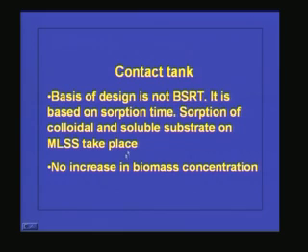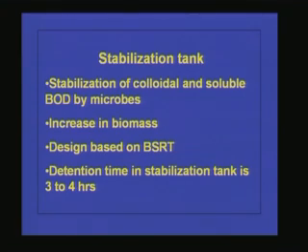And sorption of colloidal and soluble substrate on MLSS takes place. Though there is a slight increase in the biomass concentration, because soluble BOD is present and we are giving an aeration time of 30 minutes, we are assuming that no increase in biomass concentration takes place in the contact tank. And in the stabilization tank, what is happening? Stabilization of colloidal and soluble BOD by microorganisms is taking place.